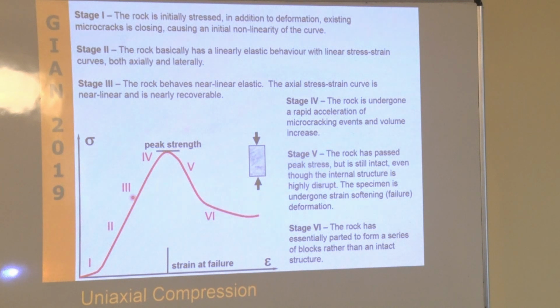So in mining, you have two things, especially in hard rock mining, that we want to avoid. One is the brittle failure, because that is abrupt and releases energy, too much energy that could actually kill you. I'm not joking, kill you. And the residual state is where fracture has happened, and the rock is sort of there, it's fractured, but it's quiet, doesn't explode anymore.